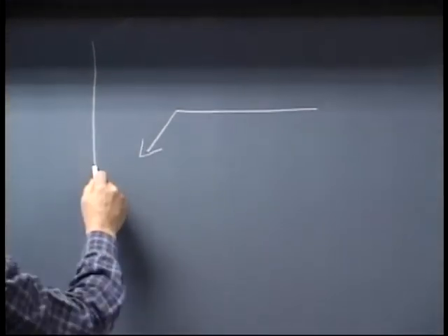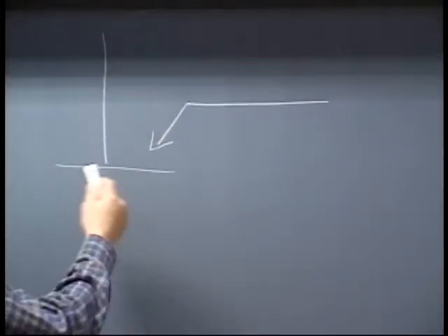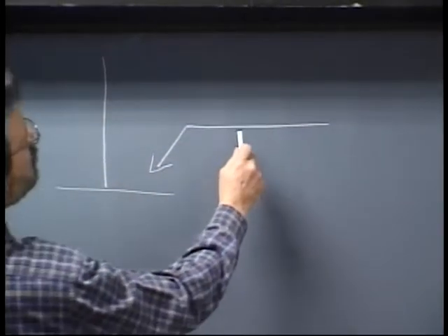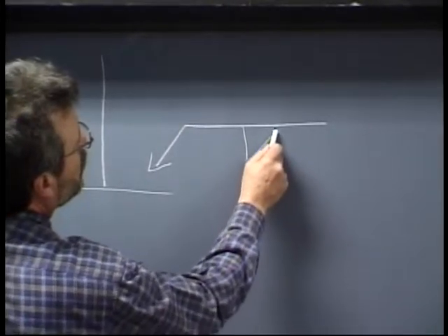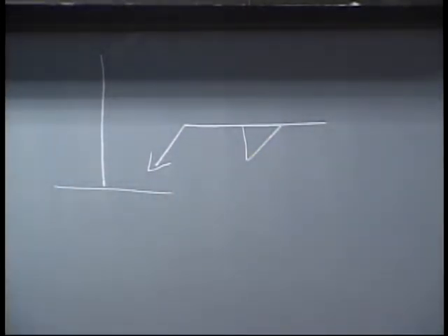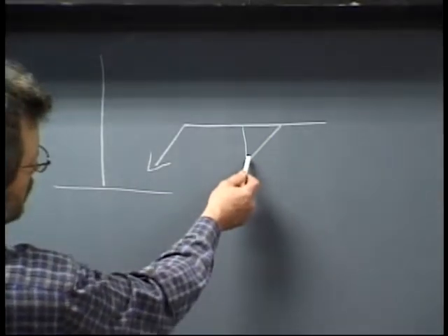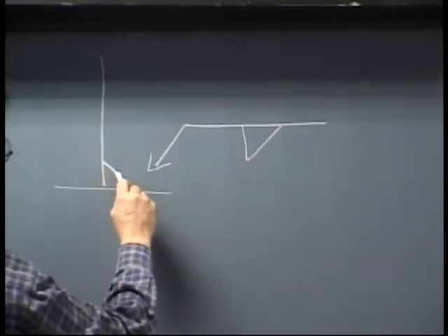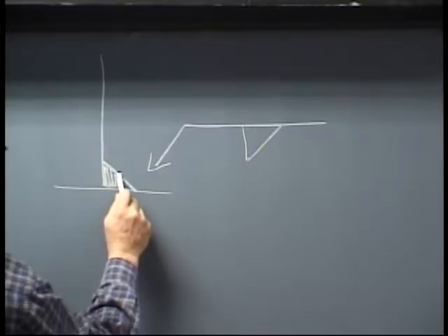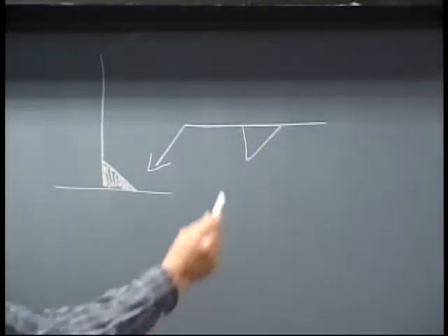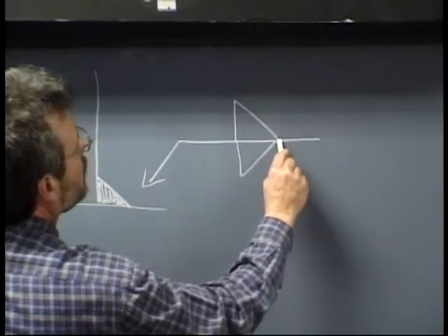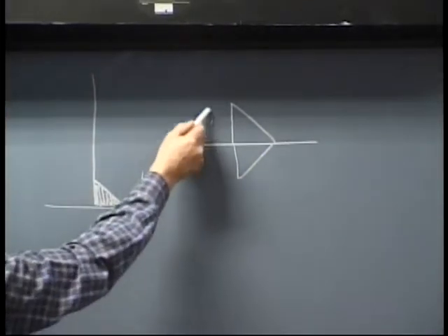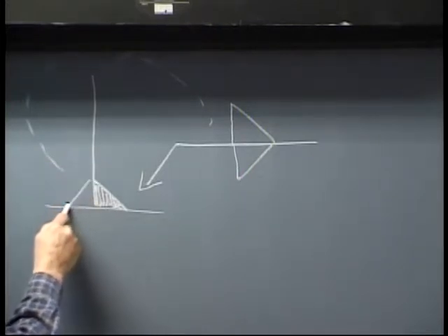So let's say, for example, we had a T-joint. Okay? So we're going to have that T-joint, and we're going to put a fillet weld on it, just like you've been doing in Weld 1755, 1760, Weld 1950. Those are all fillet welds. Well, if I put my fillet weld symbol below the reference line, that means that I want this weld made on the arrow side of the joint, right here. If I put a fillet weld symbol above the reference line, it means that I want the fillet weld made on the other side of the joint.